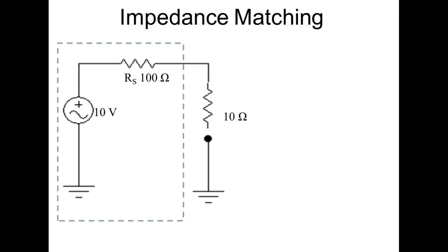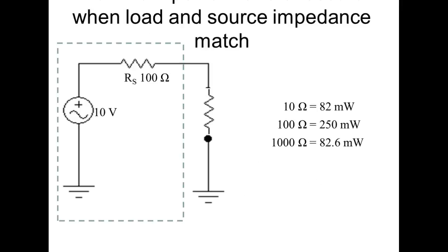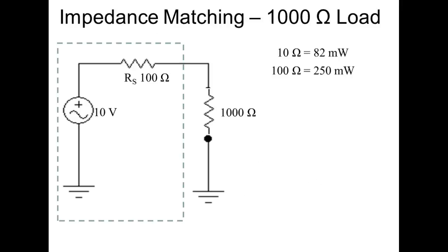But I can't connect the output of a common emitter to a low impedance load, like speakers or relays or stuff like that, right? You understand that? Because they need a lot of what? Current. That makes sense. Because what are we shooting for? Impedance, what we call impedance matching. So that's a good test question.